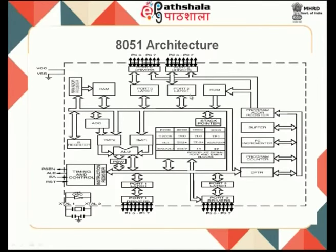We will have memory here, random access memory and read only memory, where we will have all the special purpose registers. This is very important, as it may not look similar in other architectures. In this 8051 we have PCON, SCON, TMOD, the interrupt enable register, SBUF for serial communication, and we will have timer registers. So many registers are also available.